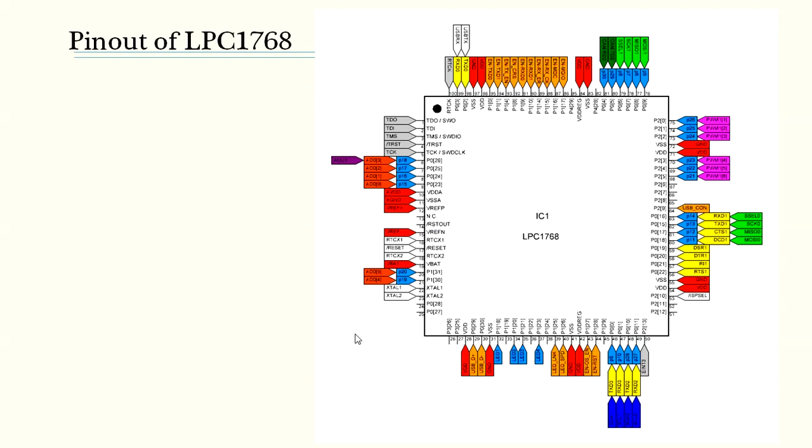The GPIO of LPC1768 is the fast general purpose parallel input output. The device pins that are not connected to specific peripheral functions are controlled by the GPIO registers. These pins may be dynamically configured as inputs or outputs. Separate registers allow setting or clearing of any number of outputs simultaneously. The value of the output register may be read back as well as the current status of the port pins.